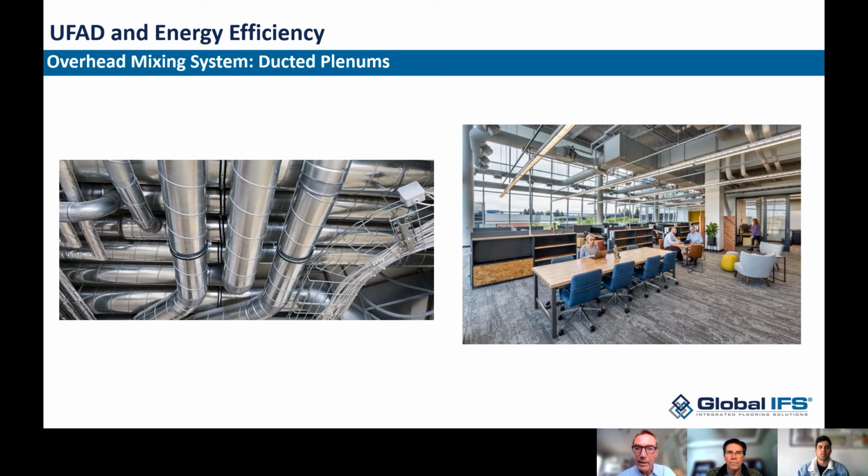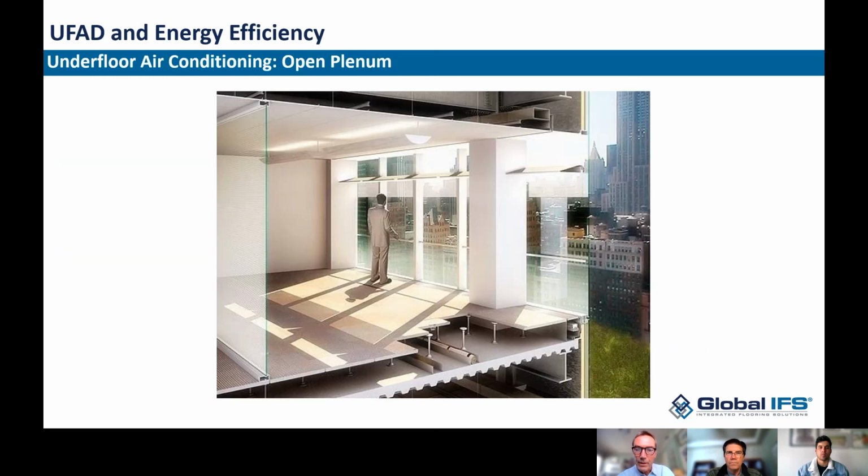So with an underfloor system, we can really remove all that noise in the ceiling, if you will, and put it down under the floor, eliminate a big part of the ducting that's required to service that space. And here's another good visual of what it looks like with an underfloor system, where, again, as I mentioned earlier, we're either eliminating or vastly reducing the amount of support ducting that's needed to supply the space. And whatever we do need, we can put under that floor and leave a nice clean ceiling. Particularly plays well with mass timber. We're really trying to highlight that beautiful wood finish in the interiors.